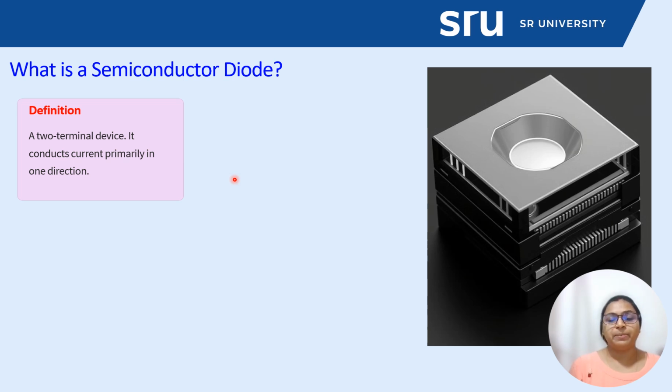At room temperature, the thermal energy excites electrons across the band gap. It generates electron-hole pairs, and in an intrinsic semiconductor, the hole carrier concentration and electron carrier concentration are the same. On the other side, we create an extrinsic semiconductor intentionally by adding impurities, or doping. Based on our wishes to apply them in various applications, we dope the material.